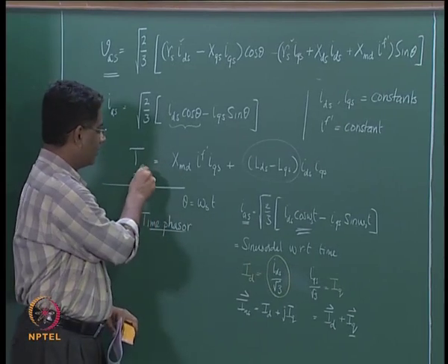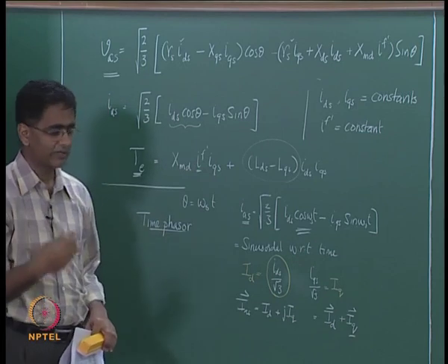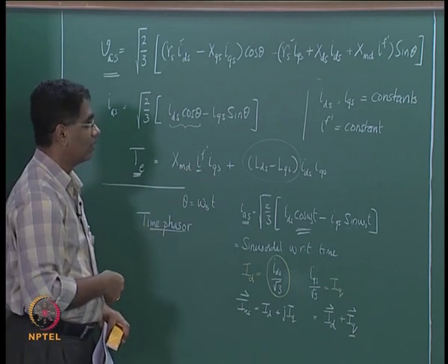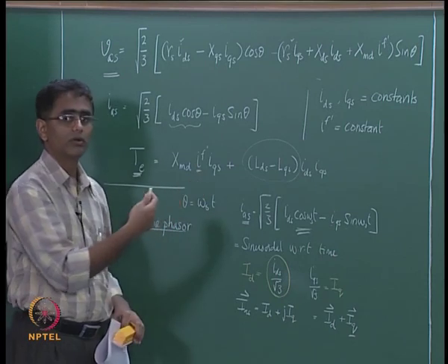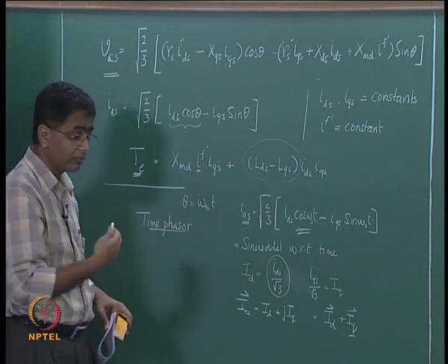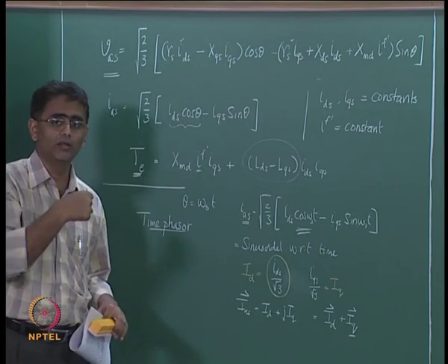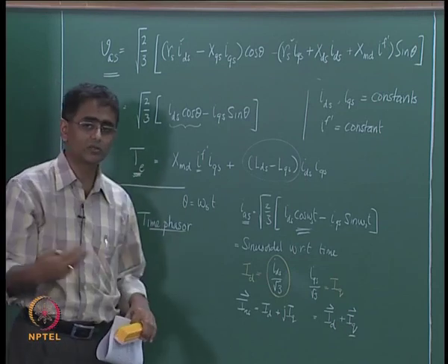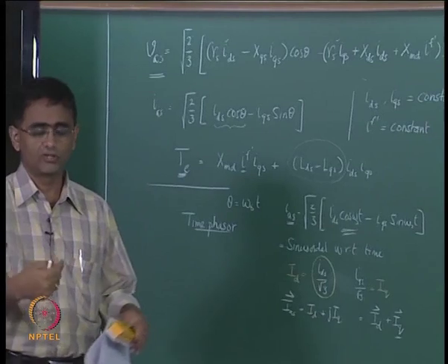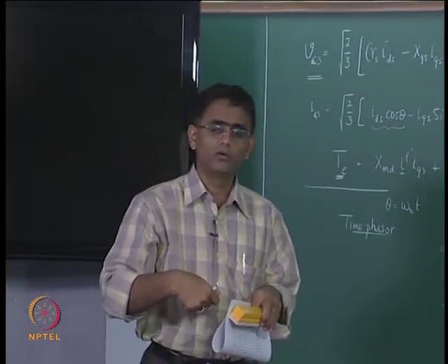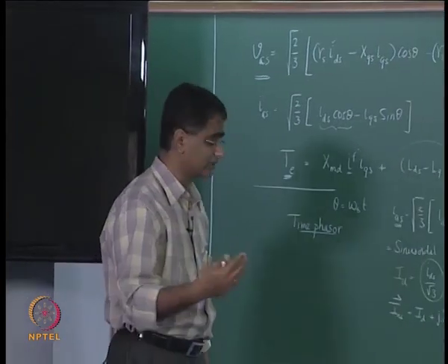then if you increase IF, field excitation alone, IQS is not going to flow because of that. If you are not increasing the mechanical input, TE still has to be 0, because TE has to be equal and opposite to the mechanical input shaft torque that is going to drive the generator under steady state.